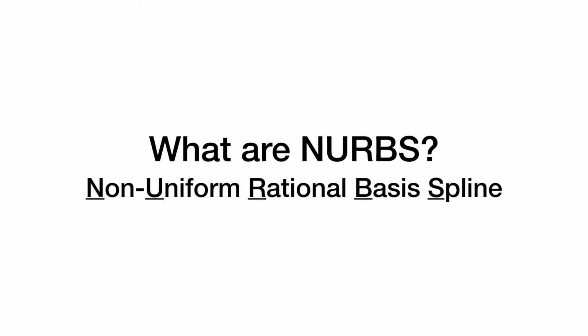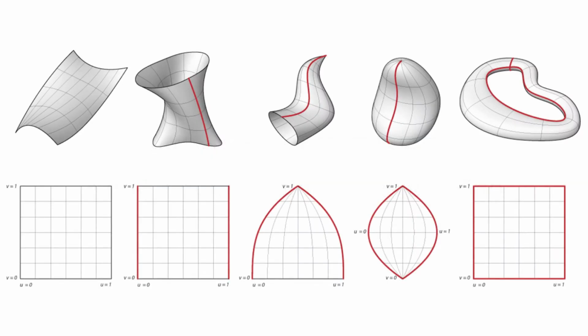And then finally, non-uniform. So we don't need to pick one mathematical function for the entire curve. We can actually splice together a whole bunch of mathematical functions. So that's where the non-uniform comes in. And we're not limited to one plane. We can go in the x, y, or z axis as we have this equation. And they all kind of are smooth and nice together. So by combining these different equations and then combining a bunch of NURBS curves into a NURBS surface, you can get all of this free-form geometry.